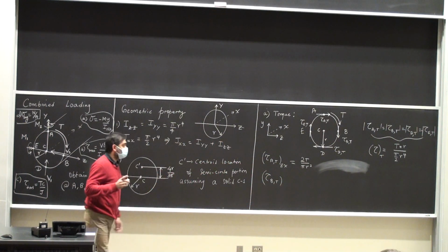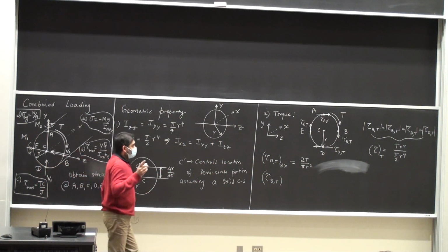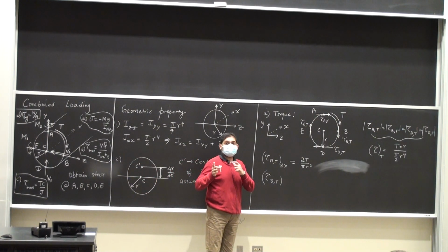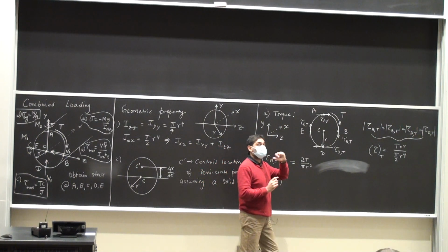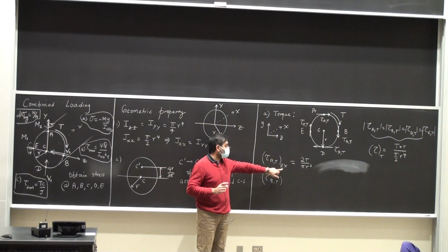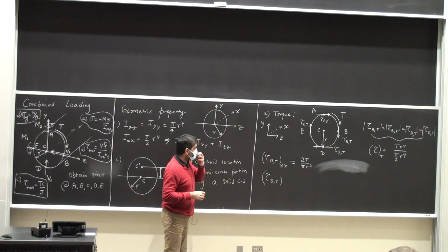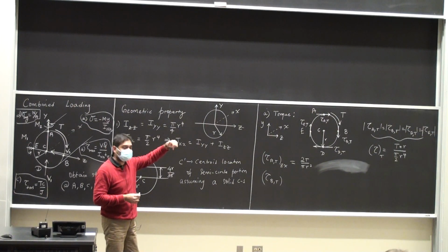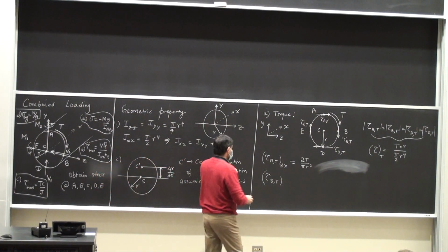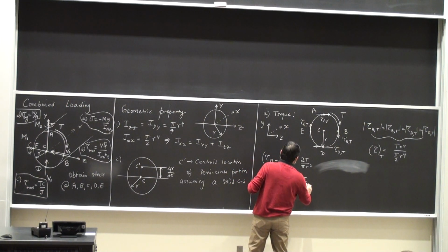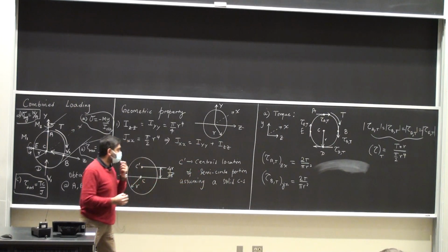B, due to the torque applied, what is the directionality for that? We don't associate a positive or a negative sign with shear stress. The arrow is a really important thing that distinguishes whether the stress is pointing up or down. The subscripts don't necessarily tell you that. So for B, the shear stress is pointing in the y direction, negative y really, but y direction. Area normal is still x, so this is tau yx, 2T by pi r cubed, same thing as before.